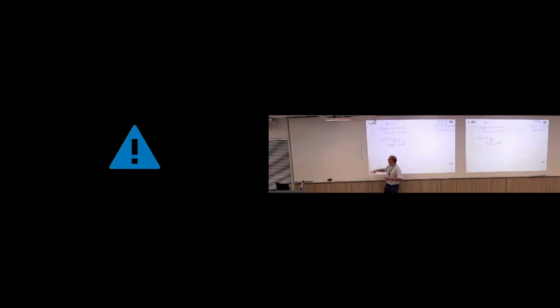CMOS, complementary MOS, we have both of these implemented as MOS technology. So what we need is something that opens if we apply a 1, so the switch is disconnected, and here something that closes if we apply a 1. I always draw the PMOS like this.